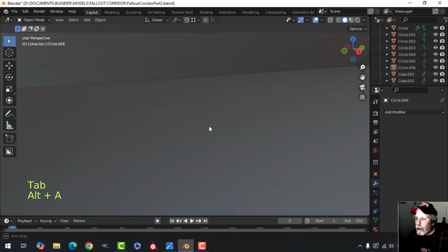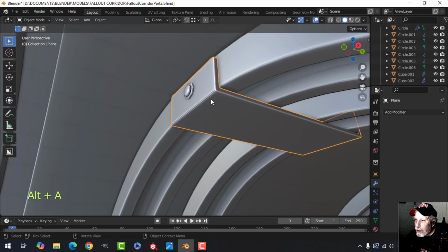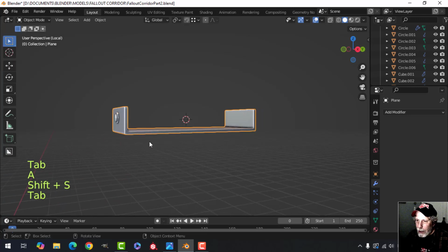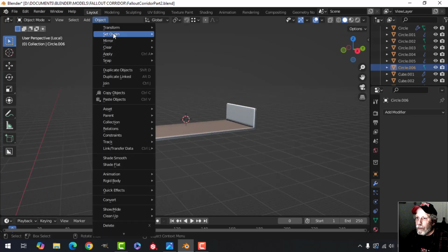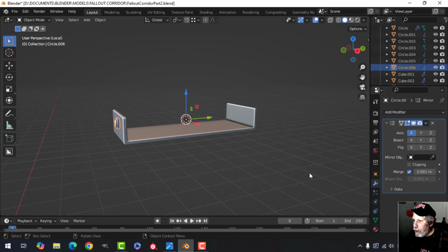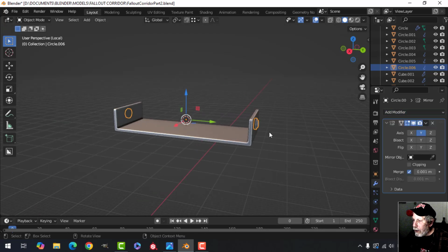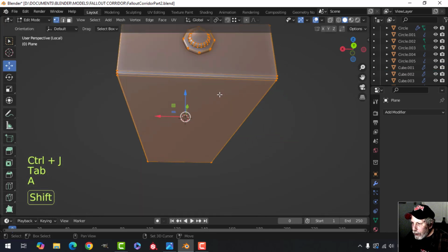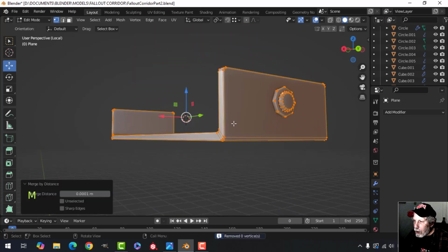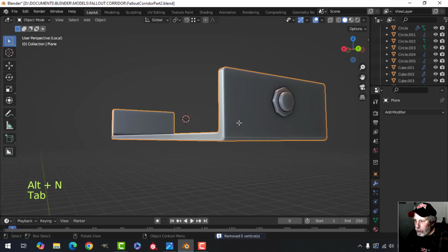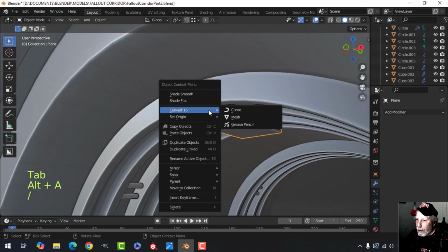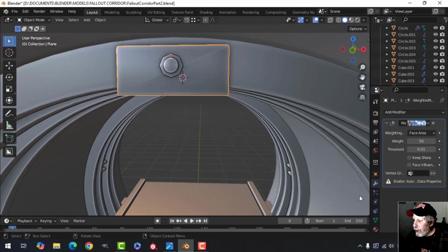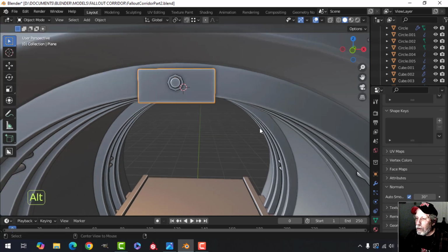And bring that in there. And then you can take this and that, focus on that. I'll just bring my 3D cursor to that, and I can take this bolt, set the origin to the 3D cursor, and mirror it like that. I'll apply the mirror, and I'll join that, and we'll see if I like it. Let's do merge by distance just in case. Alt N, recalculate outside. It should be good anyhow. If I shade smooth, I might have some shading error, so maybe I will go ahead and add this stuff. Weighted normal, not normal's auto smooth.